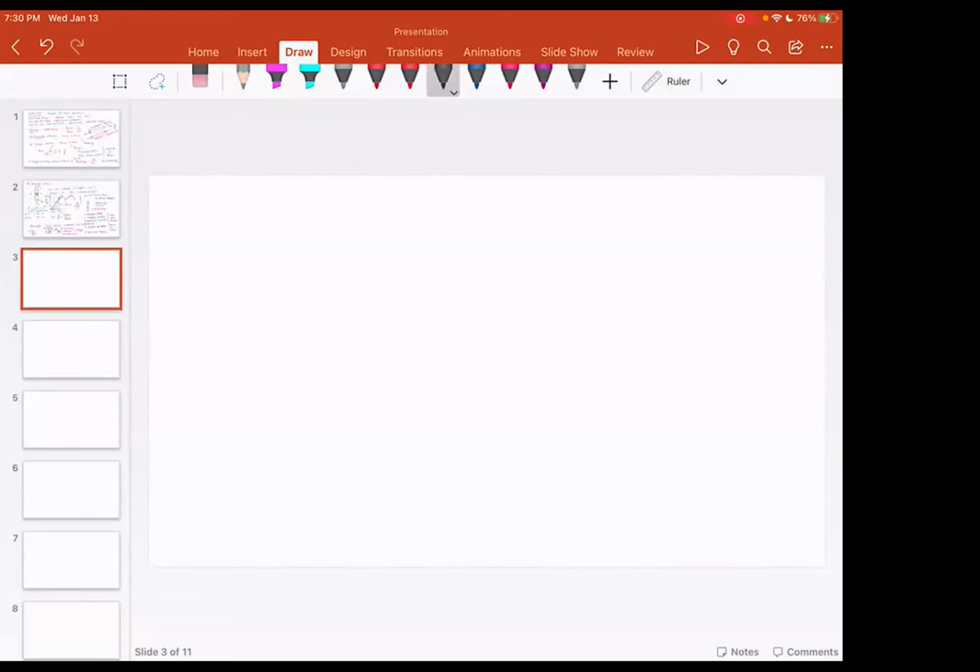Okay, welcome back. Now what I want to do is continue the discussion and extend the similar concept to shear stress. So when you have shear stress, you also have deformation, but the deformation is not along the length. For example, if you have a block, and now we apply a load that is parallel to the cross-section area, the block deforms like this.